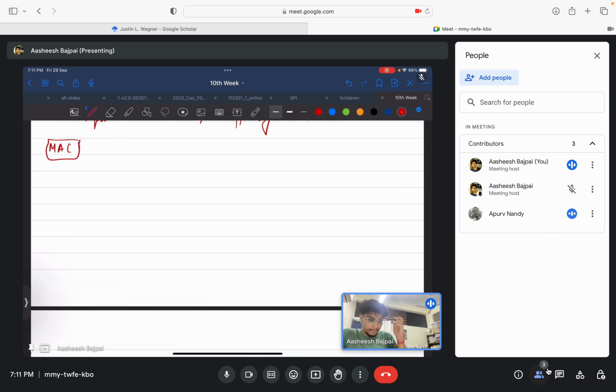So our momentum equation is du by dt. I am writing in one dimension only. Then the advection term. I am not writing all the terms here. I will write u du by dx as the advection term at the nth time step. And my del p by del x plus the viscous term. I will also not write my viscous term here because it is difficult to write again and again. It is easier to understand this way. So this is what we call our momentum equation in the x direction.